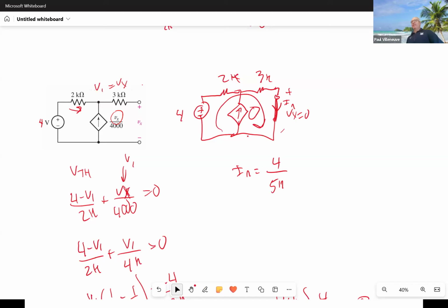Make sense? Don't make sense? Again, you immediately start laying out the circuit and go straight to nodal analysis because that's what we did before. But if you slow down and realize that there's no current going through there, no current going through there does not mean a short circuit, does it? No current going through there really means it's equivalent to an open circuit. So don't think that you can replace that with a short circuit. You cannot. Go ahead, Luke.